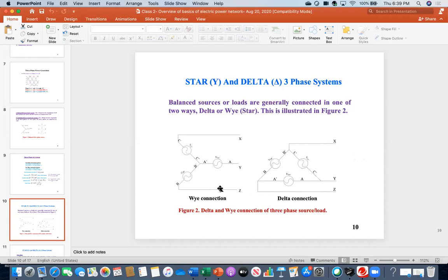So, as Venkat was saying, in the power plant itself it is the Y connection, and immediately after that there is a transformer. After the transformer, typically the delta connection is used. But once it is the distribution portion, most of the distribution lines are again Y connected, because people need to use power and it requires the neutral; you cannot connect neutral here.